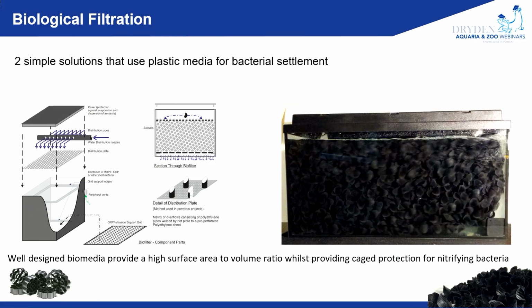And people might think that because there's lots of water passing through your filter, it's well irrigated, but because of the density of that surface area, the density of bacteria can be huge. The oxygen demand is much greater than the water can supply, and therefore anaerobia in the filter is inevitable. So media that's well colonized by bacteria is where we're coming from at the end of the day. This is where it should happen.